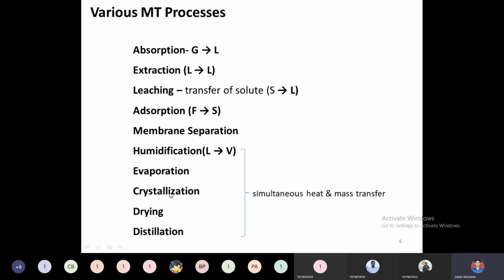In the sugar industry, the crystallization setup is the heart of the industry, because after extracting the sugarcane juice, it needs to be concentrated with triple effect evaporators or multiple effect evaporators. Then it will be sent to the final unit called the crystallization unit. What will happen there? It will be heated up to the saturation limits, up to a super saturation, and it forms a solid.